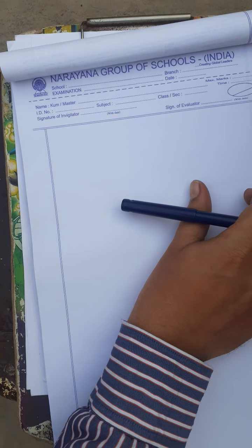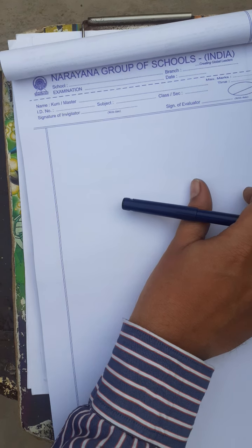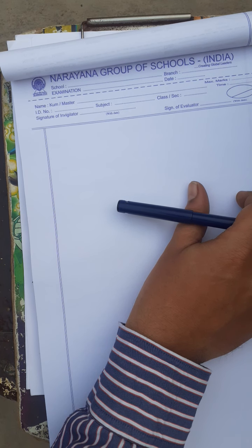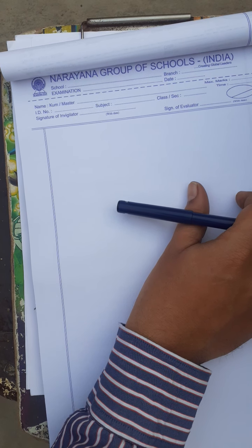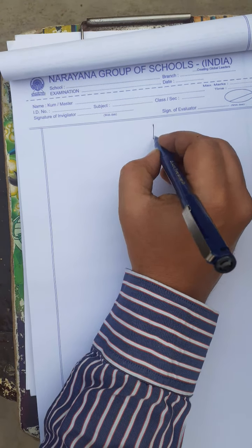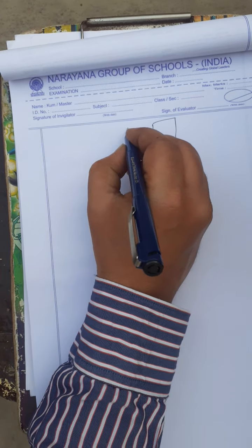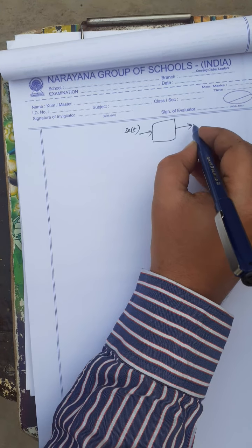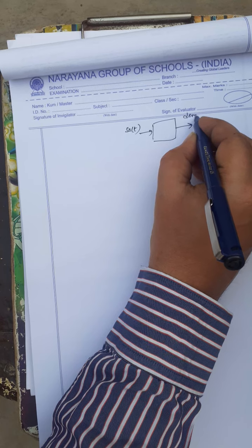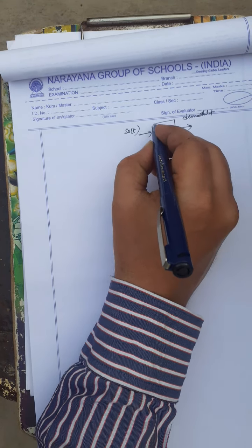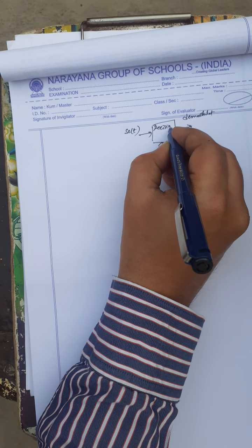So the output of the integrator we are giving to the decision device, where it compares the output of the integrator with the internal level of threshold voltage. So the decision device has one input, S0(t), and the output is the demodulated signal, with an internal threshold level. This is a decision device.